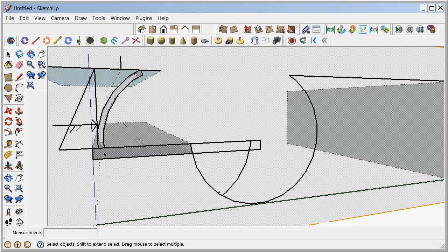And if you think about the free body now being essentially the line here, down, and then the dam, you now have summarized all of the hydrostatic forces acting on that dam. Here's the fun part about a circular gate, however. All of the individual forces that are pushing on this gate, all of the individual pressures, have to act normal to the gate. That's the definition of pressure with the fluid when a fluid interfaces with the surface. And so what you have is a whole bunch of forces and pressures that are acting through the center of the circle, which means they have no torque or moment.